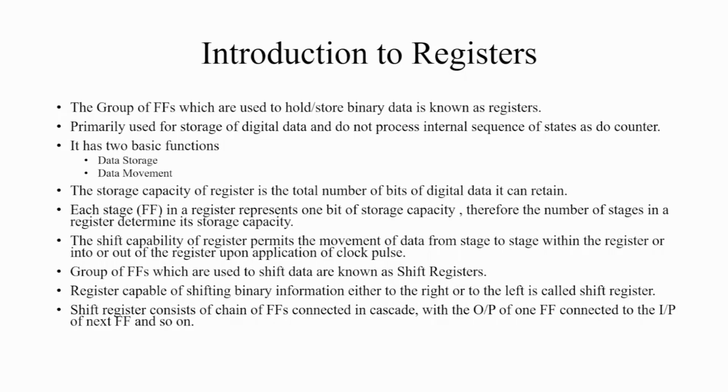In today's lecture, we will discuss the meaning of registers and shift registers. Here we talk about a special type of register generally used in digital electronics for data storage and data movement. It is primarily used for storage of digital data and does not process an internal sequence of states as a counter does. Generally a counter processes an internal sequence of states, but registers are used as a storage device, not to process an internal sequence of states.